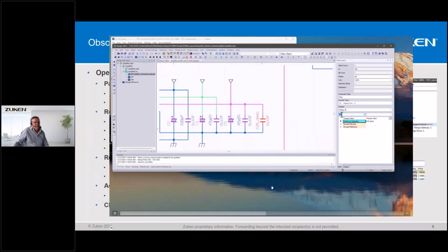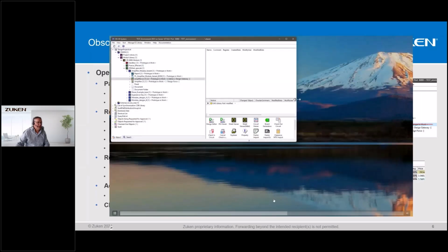Also, and this is an essential part, as I'm changing the module, I will later on also change, of course, the layout module. So I need to tell that component what is your layout module name, the reuse file name, which is the reuse layout name, and what is the reuse reference designator, which is in this case, of course, the same, which is C25 _ demo. This is my original name. Okay. We are done with that.